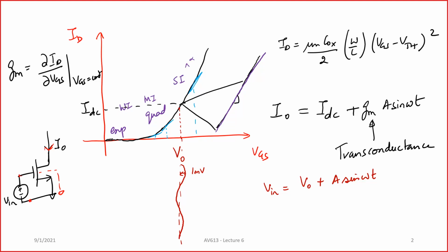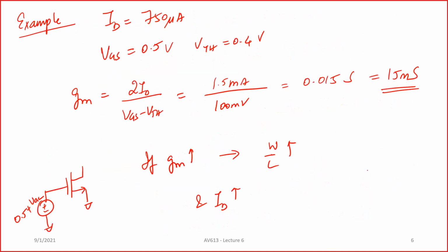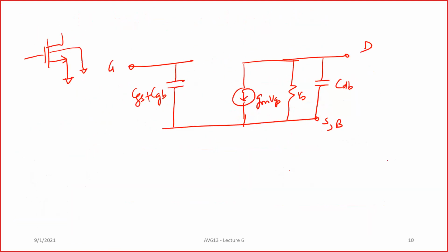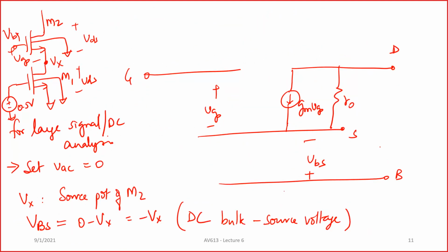All right. Any other questions, doubts? Yeah, tell me. Yeah, I can hear you now. Yeah, go ahead. Sir, I have a query: VBS only varies in a cascode connection, as you told. And it will not be varying, for example, for M1, it is constant. Yes, there is no VBS variation for M1, right? Both bulk and source are shorted together and to ground.